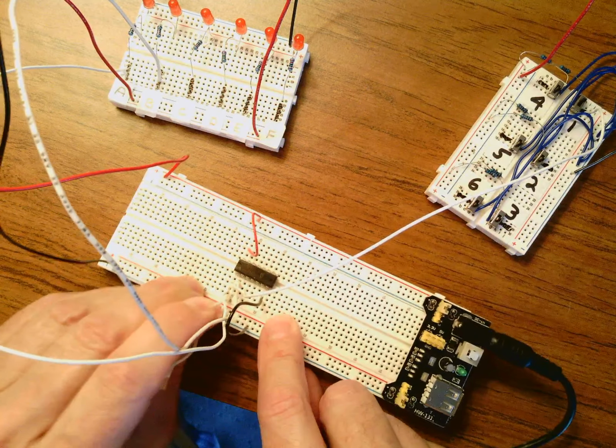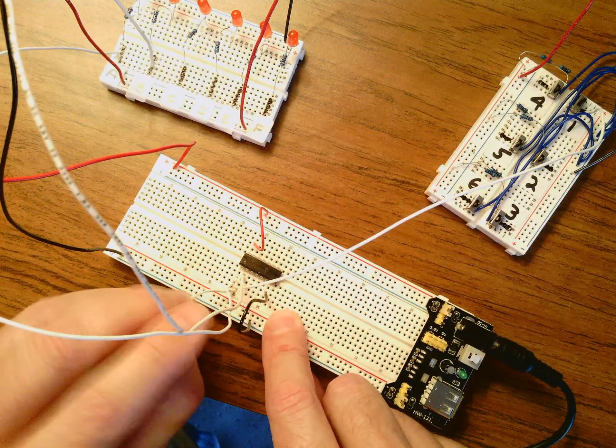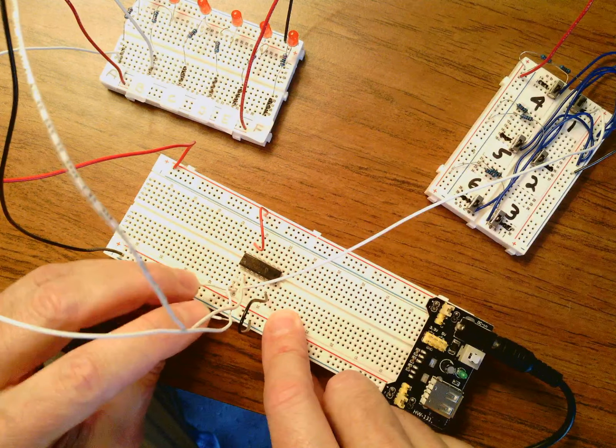So here I go to pin number 2, and I jump that to pin 3, which is the input of the second one. I'm getting this all off the specifications. You have to have your specs out to see this. I went from pin 2 to pin 3. Why did I do that? Because I'm coming out of the first inverter, and I'm taking it into the second, pin 3. Now, pin 4 is going to be the output of the second inverter, which I want to run to LEDC.